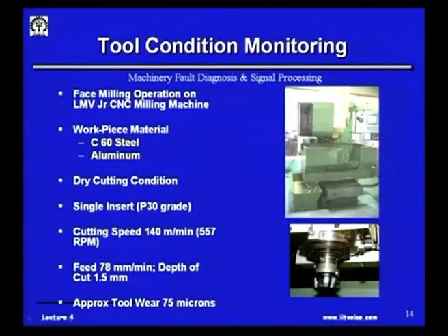In such a condition, this milling machine was instrumented with a cutting tool force dynamometer, with an acoustic emission sensor, with a vibration sensor, with a microphone, etc. And also the driving current being supplied to the spindle motor was monitored.